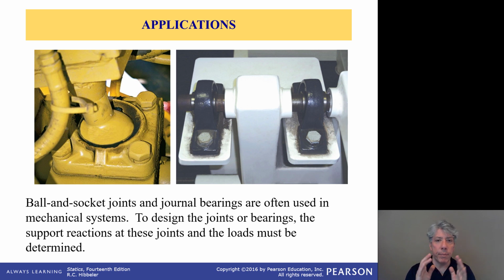Now, the bearings are interesting. A lot of times students struggle with their intuition, especially if they have experience with some of these things. If you have experience with bearings, you might know that these are called pillow block bearings, the one on the right. There's usually a set screw where you can screw the inner rotating ring onto the shaft and prevent motion of the bearing along the length of the shaft. Usually the purpose of those set screws is not so much to hold the shaft in place as it is just to hold things together. It's a fairly light grip on the shaft. There are exceptions to that, but that's the common setup with set screws.